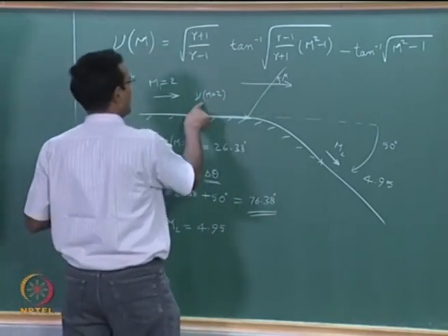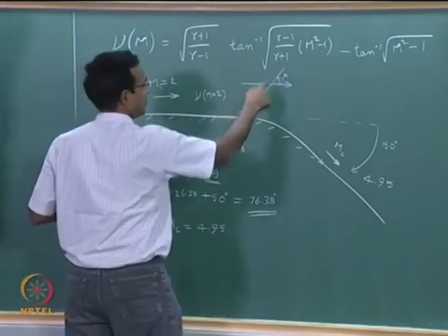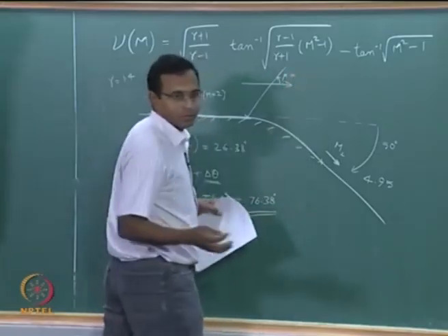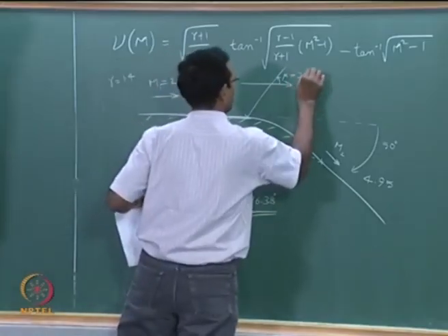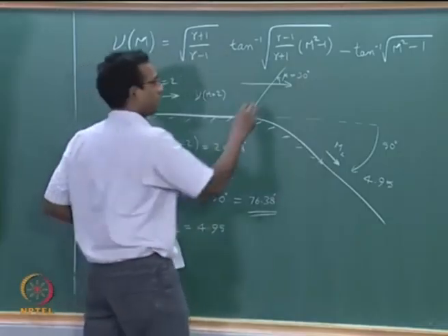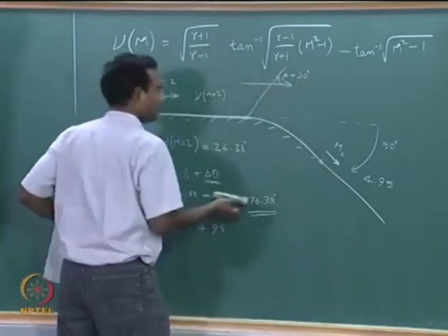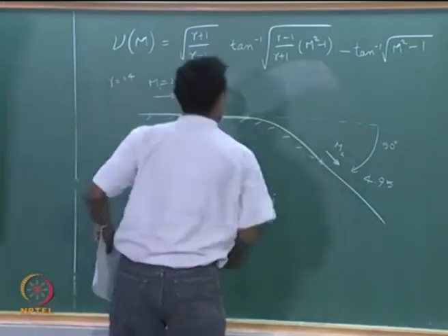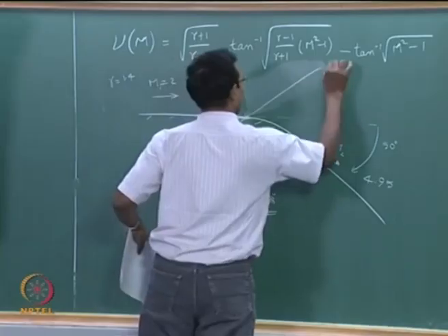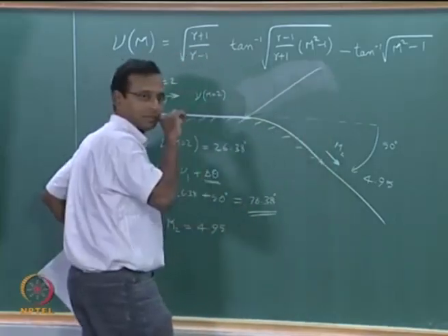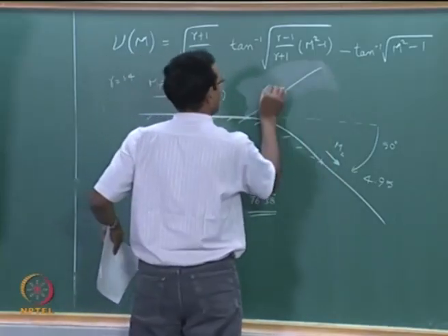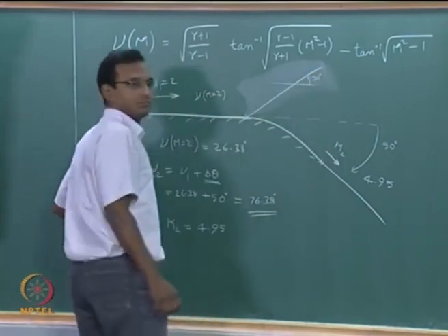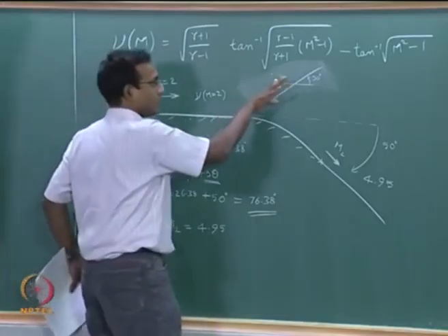So for M equal to 2, this whole region is uniform flow up to this first line. So for M equal to 2, the mu angle will be sin inverse of 1 by 2, which is 30 degrees. So it should be drawn such that it is exactly 30 degrees. Since it is not very nice, I will draw it again. We will make it look like it is close to correct. So it is going to be more like this for this particular problem. It should actually be probably slightly lesser. But anyway, this is your 30 degrees, and it is going to keep on going there.